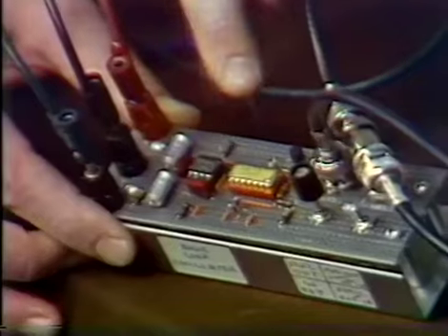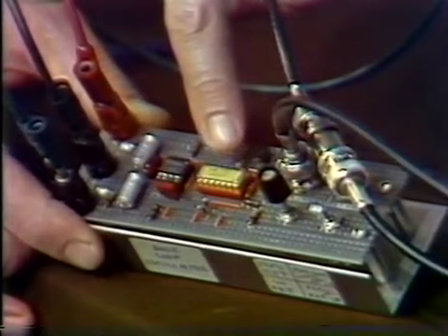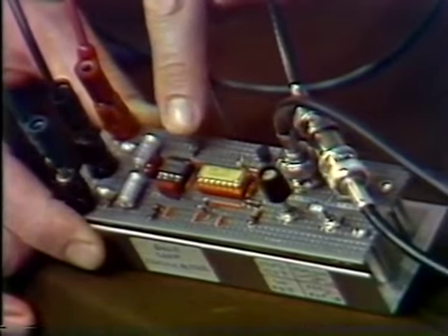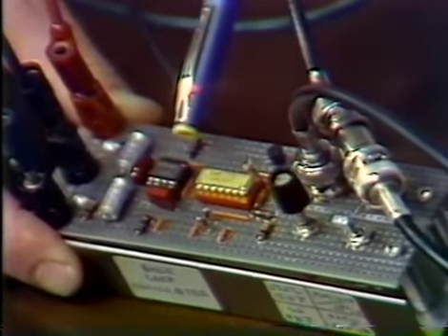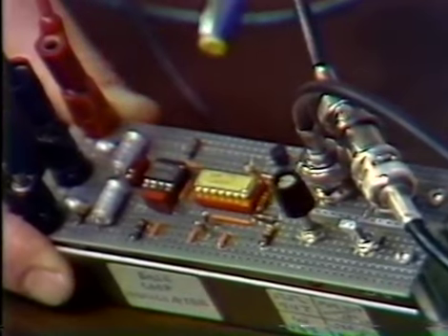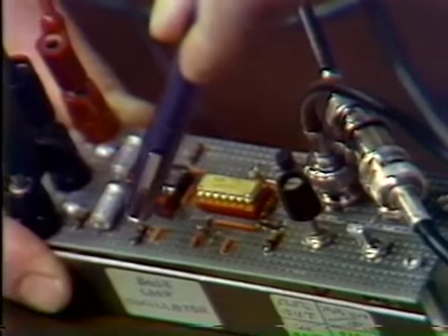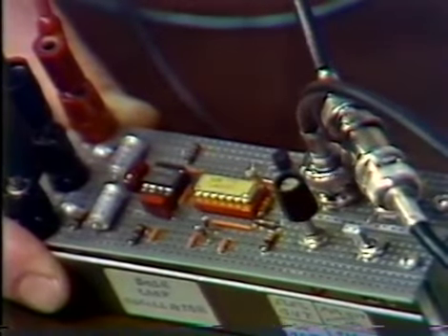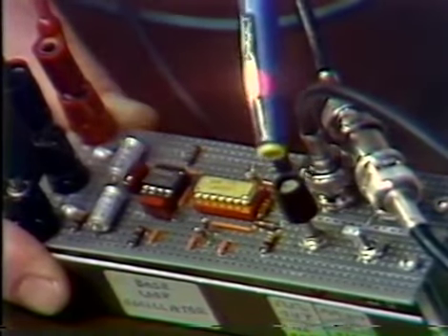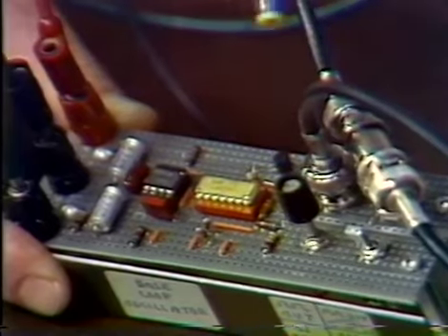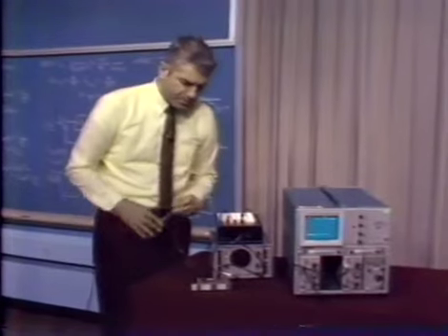Here is our home-built function generator. We actually use an integrated circuit comparator to provide the Schmitt trigger function. Here's an operational amplifier. This is the amplifier that mechanizes the integration. This is the capacitor used for the integration, and this is the resistor, or at least part of the resistor. We also have a potentiometer that allows us to change the total input resistance to the integrator, and that's what we use to change the frequency of operation. And then, of course, various output signals are displayed on the oscilloscope.